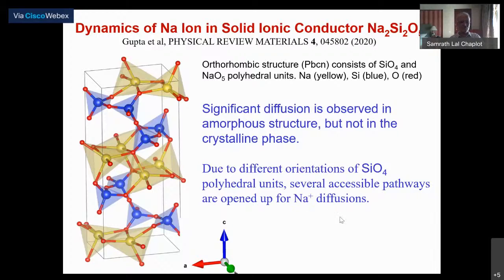The normal standard procedure is that you start with a crystal structure, but you simulate up to a very high temperature beyond the melting point, so that the atoms don't remain localized to their lattice sites, but begin having very large thermal amplitudes, and then they leave the lattice sites. In a way, you have a structure which is liquid-like. You may have to increase the temperature significantly above the melting temperature.